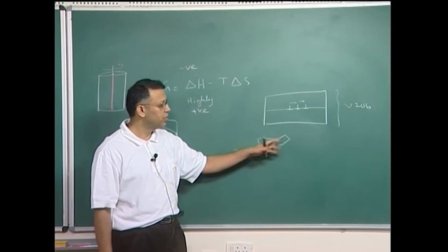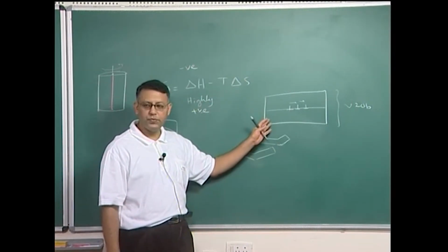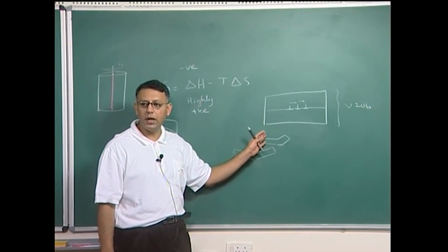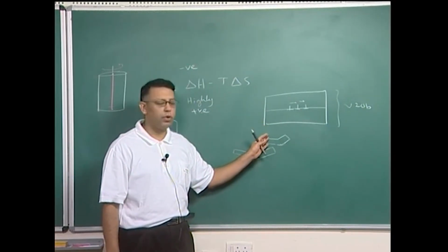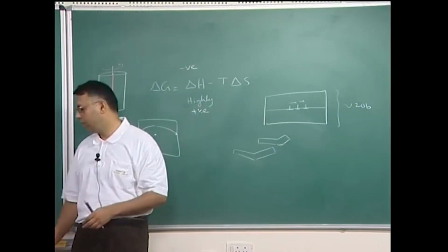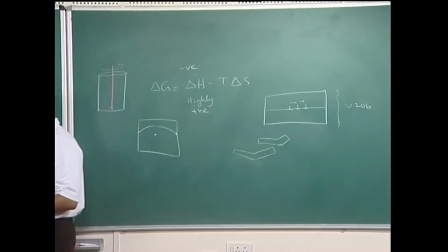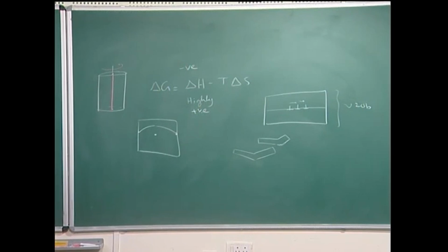This essential deformation is coming from the elastic stress fields of the dislocation. So, you can come up with strange effects: as we know, reversible and plastic do not go hand in hand, they are in fact oxymorons. Plastic and elastic are oxymorons, but you get very interesting effects like reversible plastic deformation due to elasticity when I am talking about dislocations in thin plates. Dislocations may weaken the crystal, but there are interesting effects which come because of the presence of dislocations in nanocrystals.